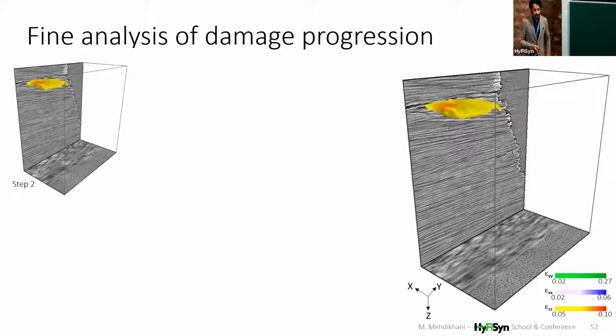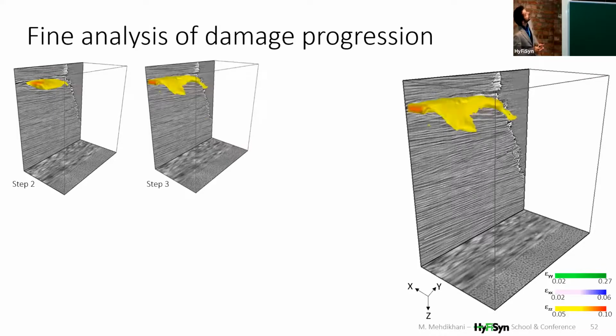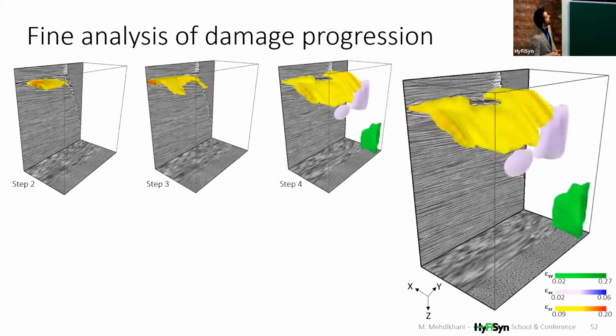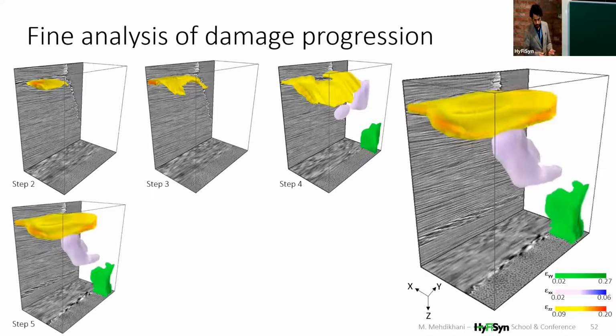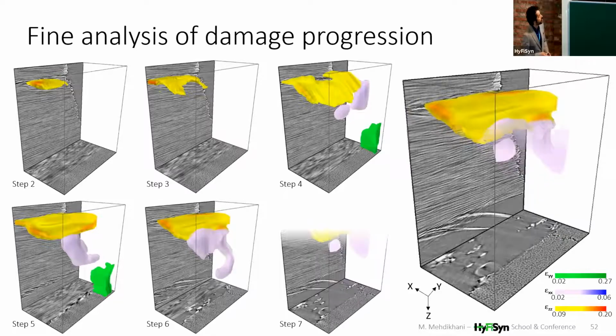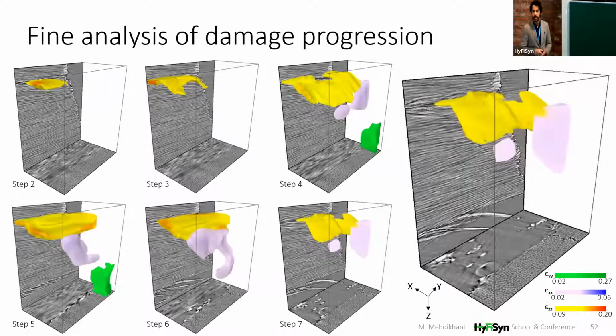We see that a transverse crack shows up here in the transverse ply, and it propagates during the specimen loading, and then we have some delamination appearing just at the interface between the 0 and 90-degree ply, with some fiber splitting, of course, in the 0-degree ply.